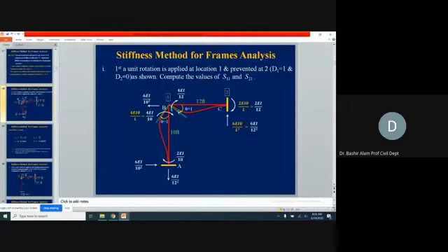So here you can see for the deflected shape of this beam, if we draw this green line as a tangent, it is a clockwise direction. Similarly, for the vertical member, this deflected shape at B, if we draw a tangent, this green line, you can see again it is a clockwise direction. Clockwise and clockwise for both, so this is according to our assumption.